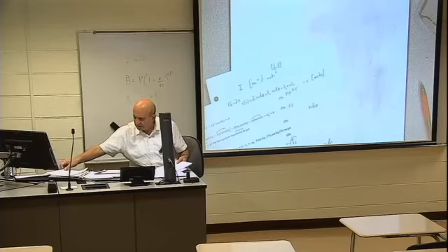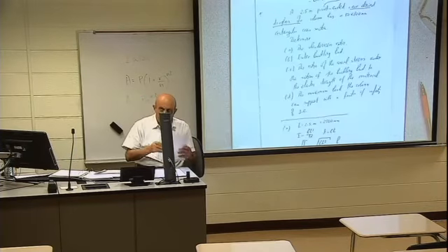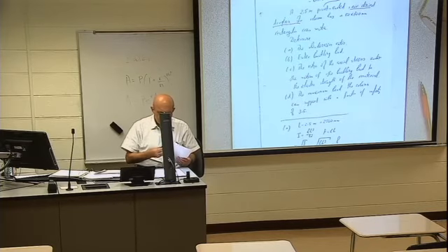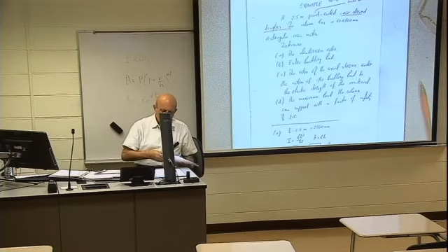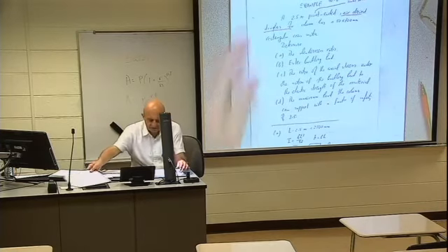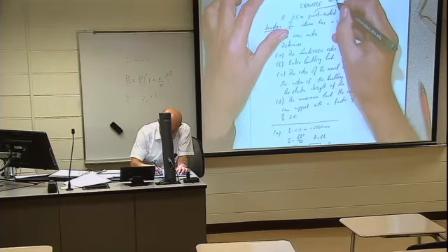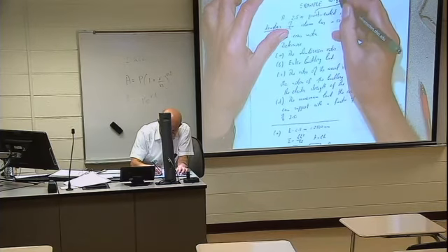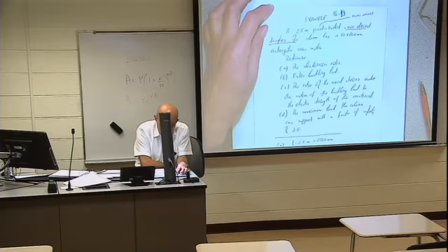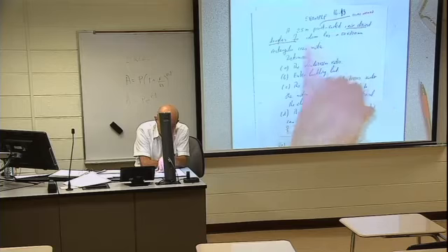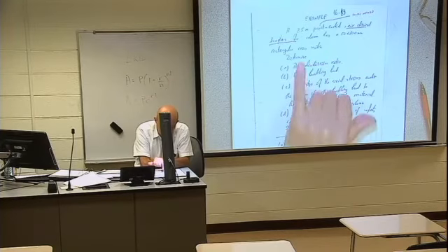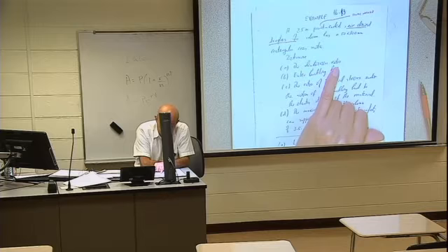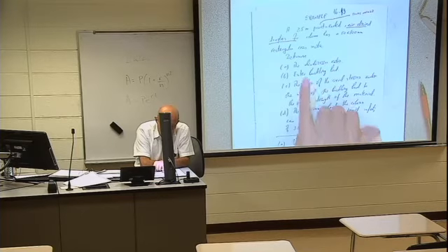And now we can proceed with an example. It is not 16.8, but 16.13. A 2.5 meter pivot-ended air-dried Douglas fir column has a 50 by 100 millimeter rectangular cross-section. Determine slenderness ratio, okay, now we know what slenderness ratio is, and the Euler buckling load.